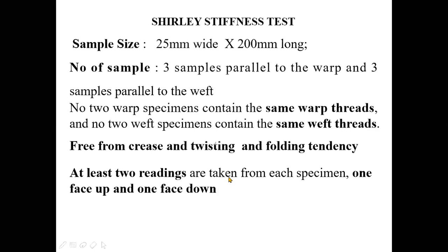Now this is measured in an instrument known as a Shirley stiffness tester. This is the sample size. You have to cut at least 3 samples parallel to the warp and 3 samples parallel to the weft. The sample size should be 25 millimeter wide and 200 millimeter long.